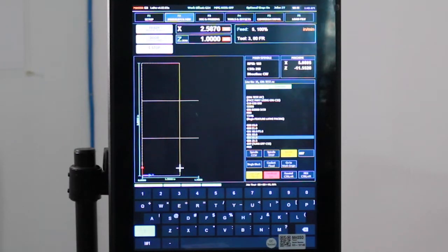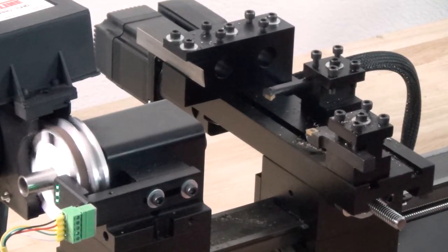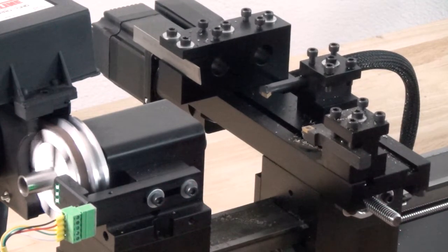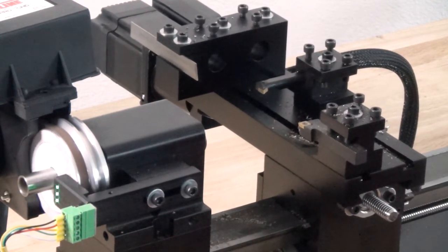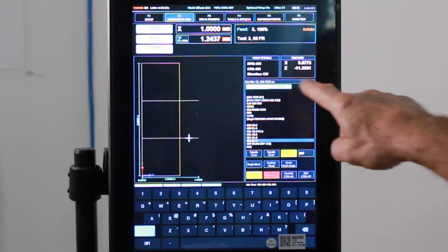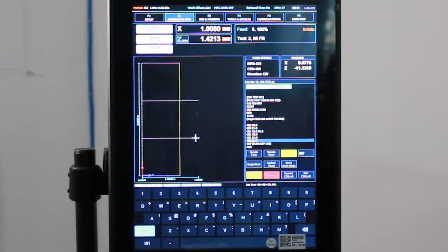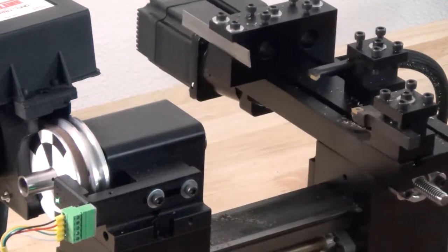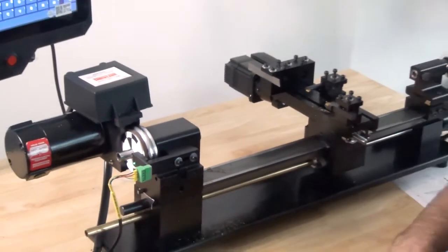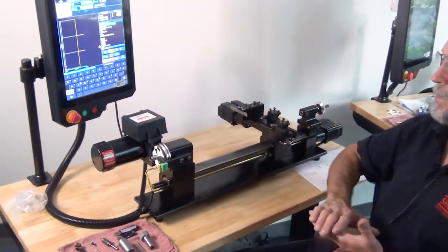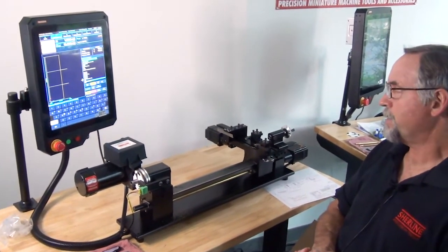Now it's going to feed back into 1 inch, and at a SFM of 180, the RPM should be right around 687. So it's feeding out, and it's reading about 672 right there. Okay, so wait for it to end here.